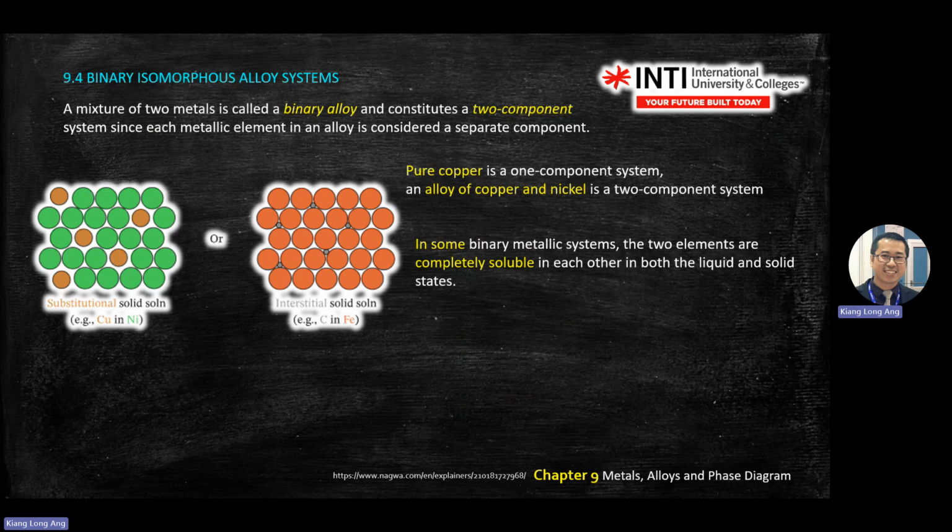For substitution you replace atoms, but must follow the Hume-Rothery rules, such as the size being within 15%. Go and read what the Hume-Rothery rules are, it's important. Both methods make the material stronger. Substitutional or interstitial, these two give you the binary metallic system.